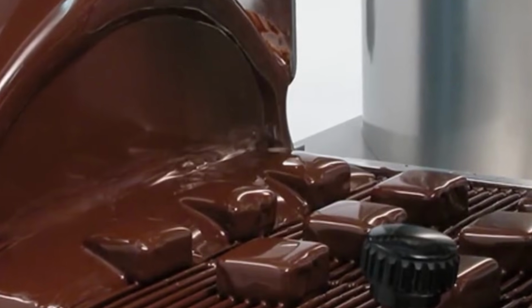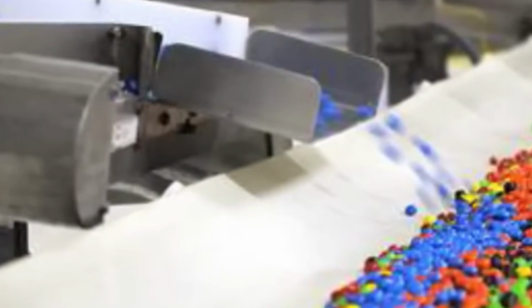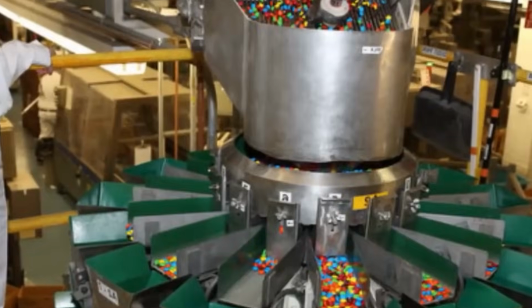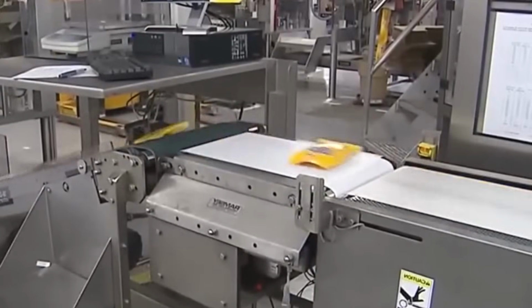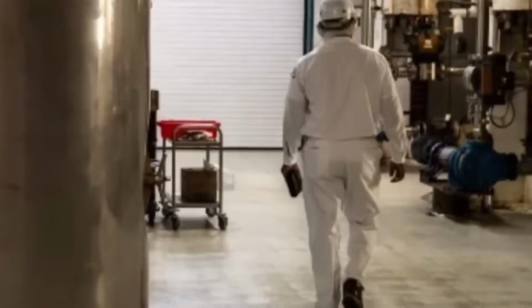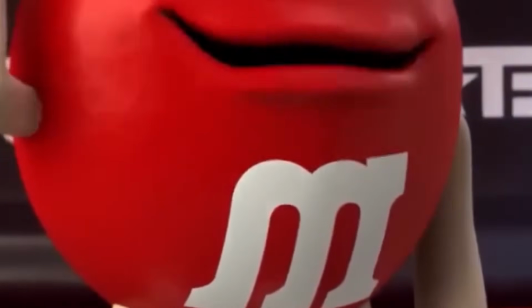Chocolate coating is conducted in automated panning drums with oscillating movement and programmable dosing cycles. Each pan receives a calibrated quantity of caramel centers and begins rotation at 18 to 24 RPM. Tempered milk chocolate is sprayed onto the tumbling centers in controlled quantities through heated nozzles. Each chocolate application is followed by a cooling phase using dehumidified cold air injection to solidify the layer before the next application. This chocolate build-up cycle continues for multiple iterations until the centers reach the specified chocolate layer thickness.